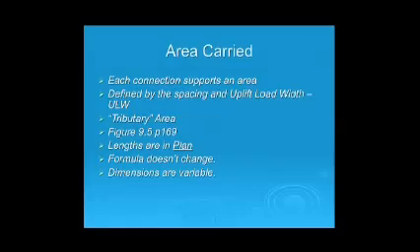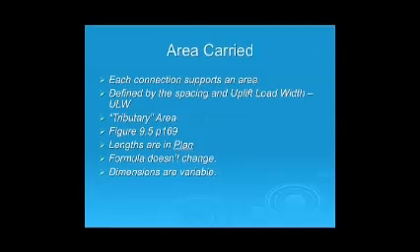Okay? The area carried. So each connection supports an area defined by ULW and spacing. ULW stands for uplift load width. That's what I was trying to show you on that beam before. Half of X was that load width. That's what ULW stands for. Lengths are always in plan. Thank God. We don't have to worry about the pitch of the roof in this case. It's in plan. So when you're working out your tie-down connections, you only look at your plan views. Don't worry about your elevations. It's only plan views we're concerned about.